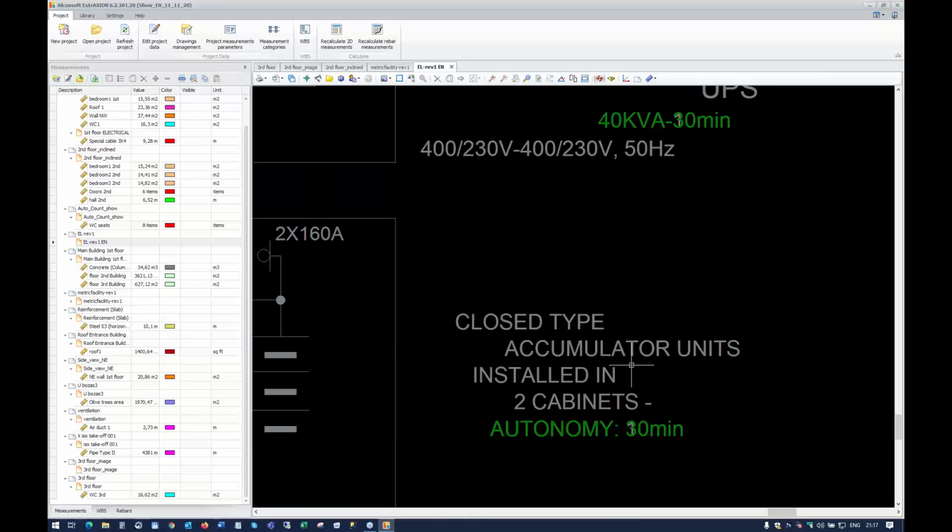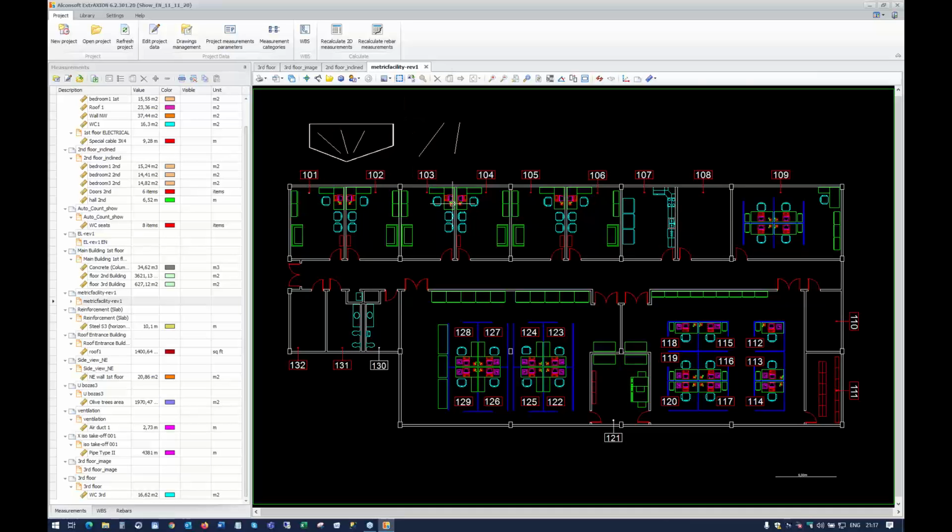So you can use drawings comparison in order to locate small differences even in text. Let's close those drawings. I will leave only the one we saw before to show you something else. Auto count. We can count automatically. So let's begin a count measurement.